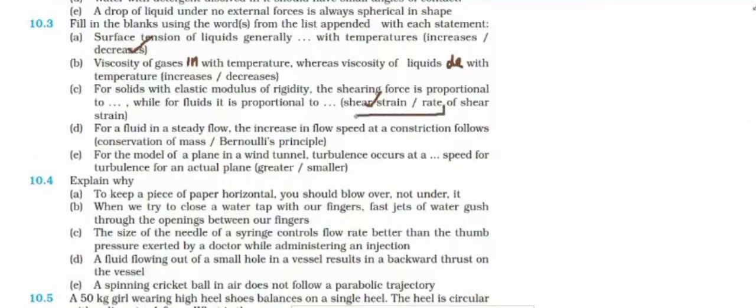When the shape of the fluid changes, it does not remain the same, it will continue to change the shape. While in the case of solids, when the shape changes, that new shape remains there. There is no further change unless another force is applied. But in the case of fluid, that's not the case. Once you apply a force on a fluid column, the change in shape will continue. Therefore, in the case of fluids, we have to take the rate of shear strain.